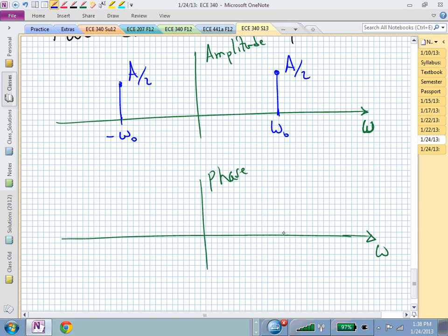We have information at both of those frequencies. It's the same frequency, just the negative of it, and I put those maybe exactly in the wrong place, but that's okay. This one, let's say, is now theta. I'm going to have to move this one. And this one now is minus theta. Our angle has odd symmetry. Our magnitude has even symmetry with respect to DC, or 0.